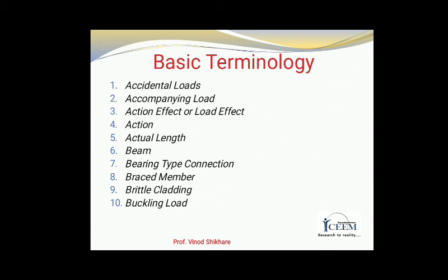Next term is bearing type connections. Connections made using bolts in snug tight conditions or rivets where the load is transferred by bearing of bolt or rivet against plate inside the bolt hole.